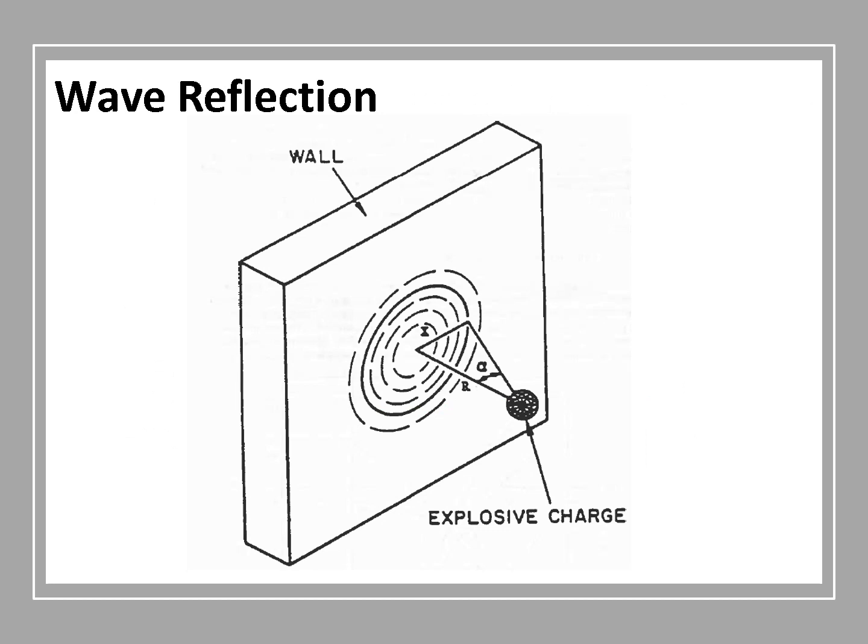As the incident wave moves radially away from the center of the explosion, it will impact with the structure, and, as a result, the initial wave, pressure and impulse, is reinforced and reflected. When the blast wave impinges normally upon the surface, then the angle of incidence alpha of the blast wave is 0. In this case, the direction of travel is perpendicular to the surface.